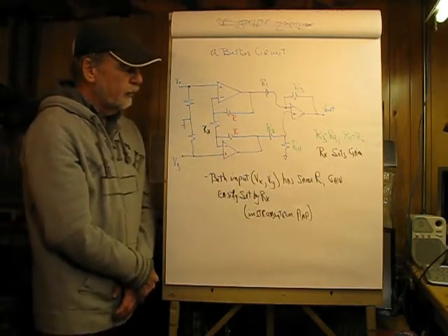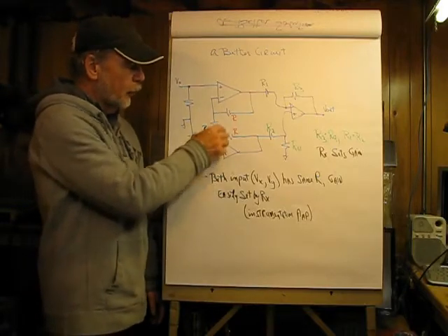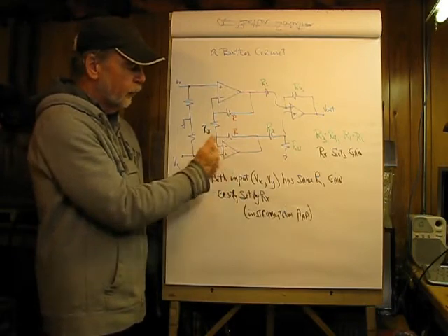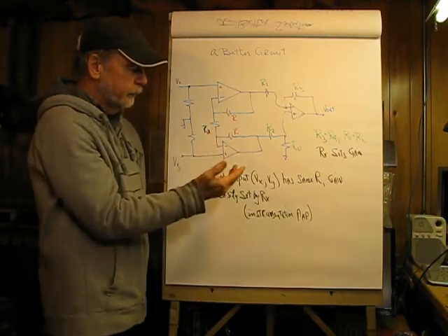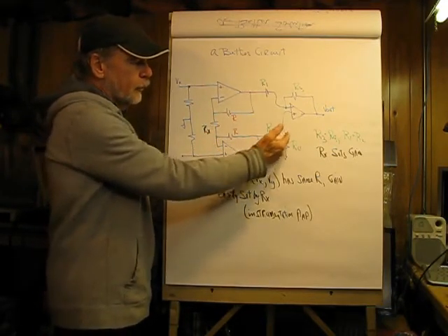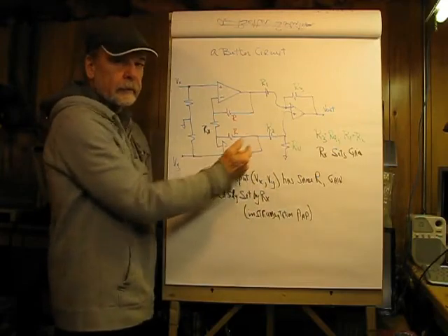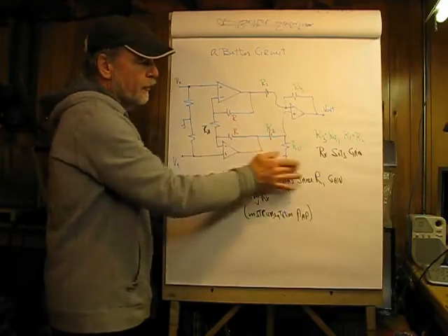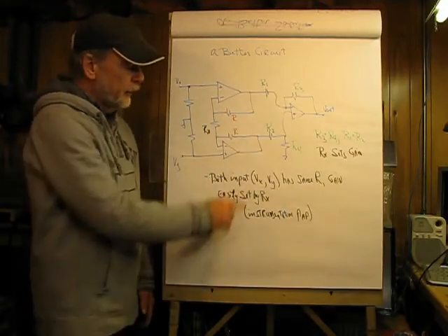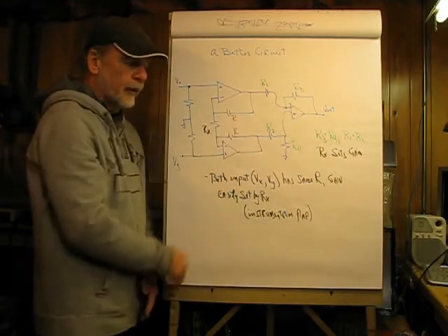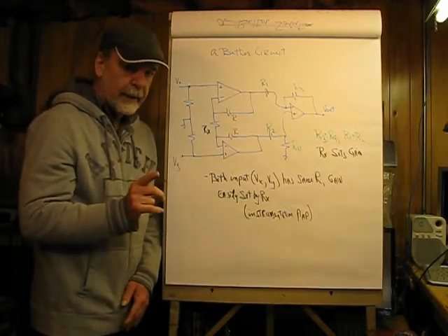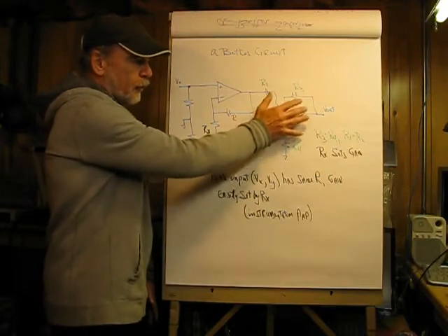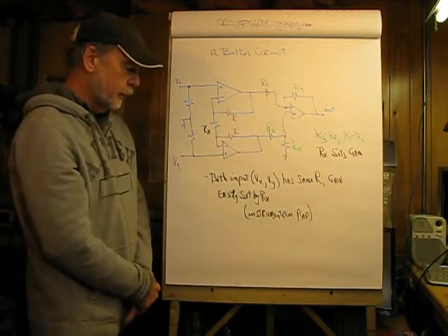And then what we see from this is we are operating these two in sort of a voltage follower circuitry, which in turn feeds, guess what? The circuit that we had on the front page. Now, the reason this circuit is okay is because the output impedance of this amplifier with feedback is very, very low. So this is perfectly fine to locate it here.